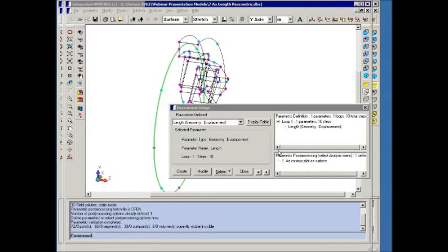The question's been asked whether we're using IES CAD or other CAD to make these models. These models were created entirely either in Magneto or Amperes or Coulomb. You could have created them, I guess, in the other CAD tools, but I'm so much more familiar with our own programs that I build them basically just from the start. I don't bother using CAD tools. We could save these, I guess, as step files. The advantage of using our own CAD tools, the built-in tools that come with the programs, is that then we know that the geometry has been constructed properly.